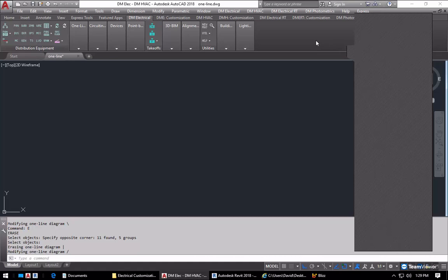In our AutoCAD software, that's pretty simple because you can create items without putting them on the drawing. Revit makes it a little bit more complicated because you have to actually physically locate your panels and transformers on your model and then connect them, and it's kind of backwards to how you actually do the design, and that's just a drawback to Revit, unfortunately.